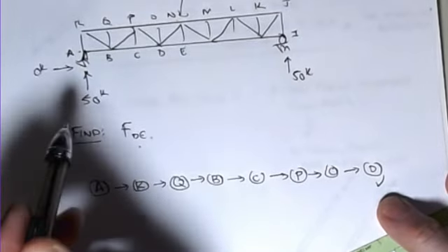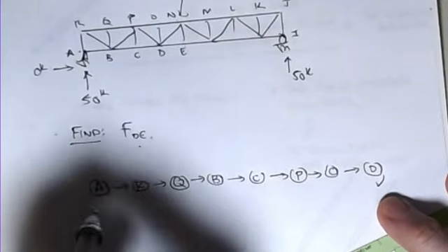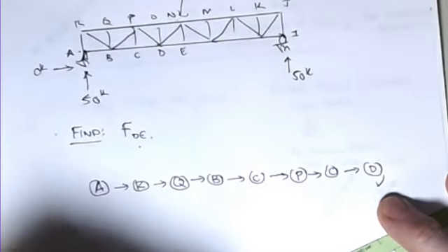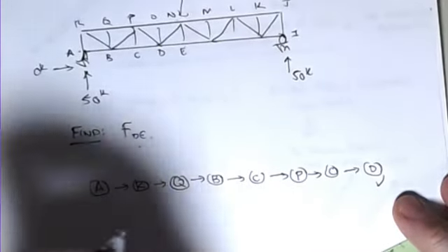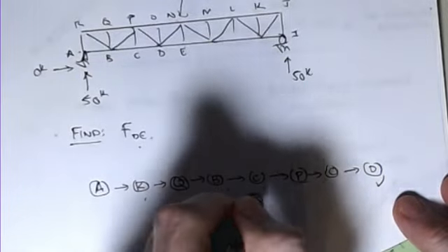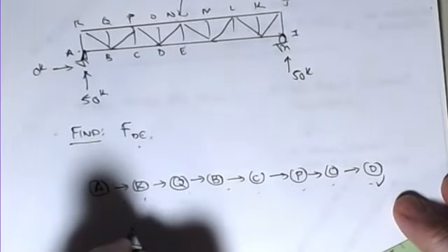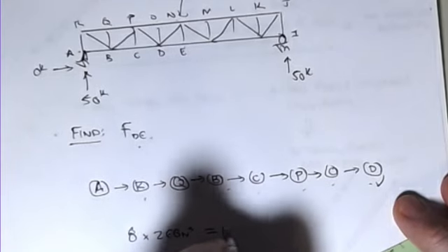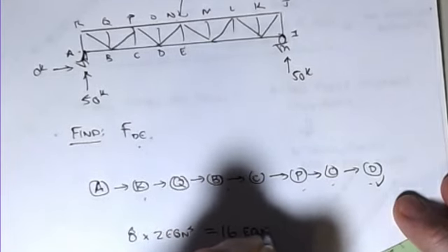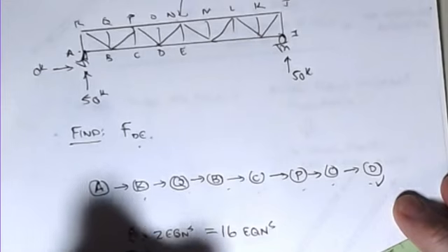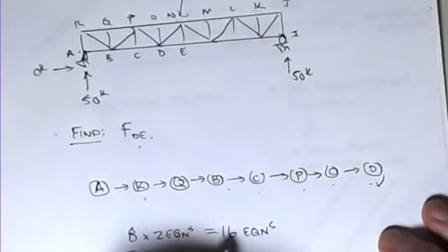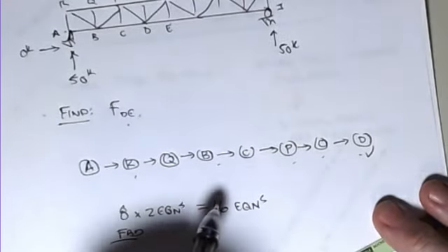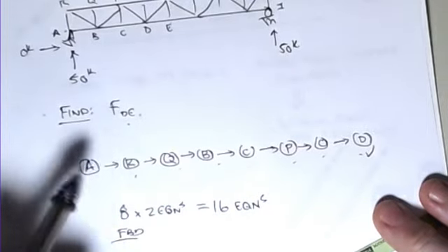Now remember, for every joint that we just went through, we have to draw a free body diagram, and for every free body diagram, I have to write two equations. So that would be 1, 2, 3, 4, 5, 6, 7, 8 sets, times 2 equations, is 16 different equations you would have to write. You'd have to do every one of them exactly right, never make a sign error, and it becomes a bit of a challenge.